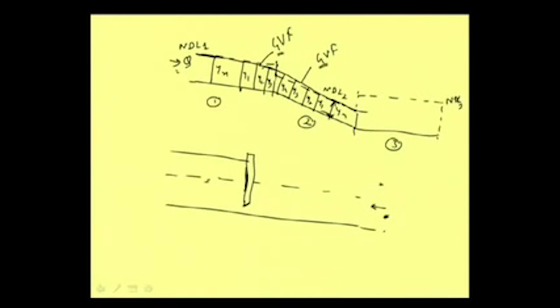So, this is one example where we are using a sluice gate, and there can be different examples, and I am stating just one. And then when this water level comes down after flood time, when the main river water has come down, then we again release the water, because in this small channel also water was flowing, and there will be some accumulation of water due to rainwater and all on this side. So, that water we need to release once the water level comes down here. So, suppose we are releasing the water.